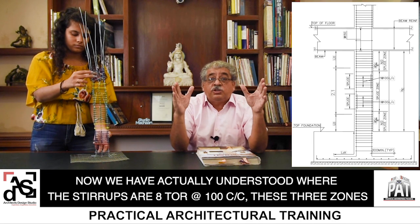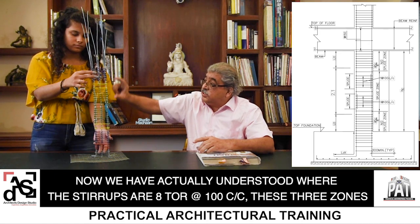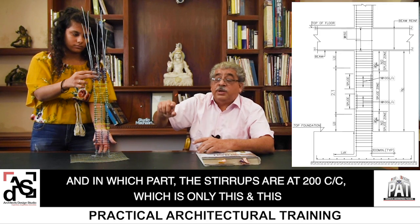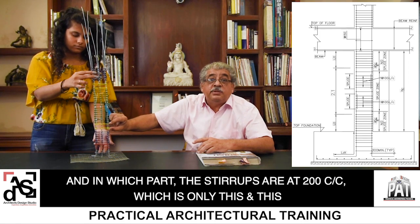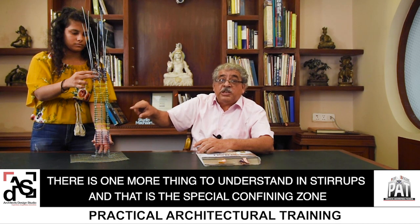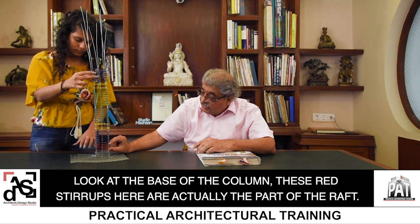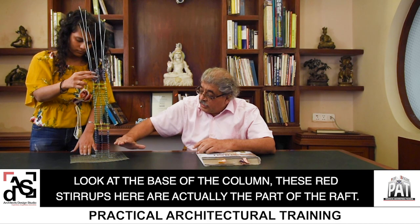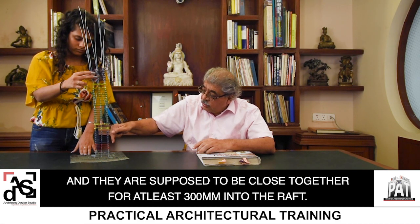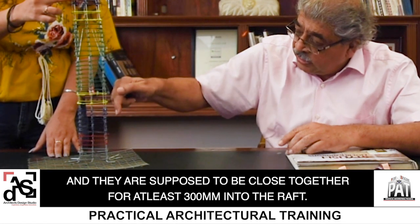Now we have actually understood where stirrups are at 100 center to center, these three zones 1, 2, 3, and in which part stirrups are at 200 center to center, which is only this and this. There is one more thing to understand in stirrups, and that is the special confining zone. Look at the base of the column. These red stirrups here are actually part of the raft, and these stirrups are supposed to be close together for at least 300 mm into the raft.